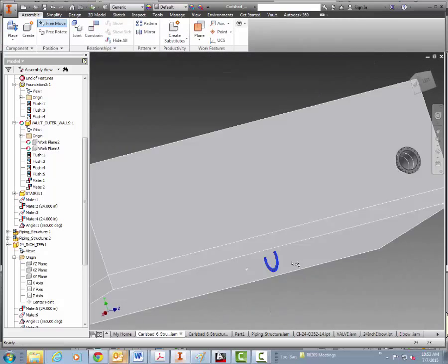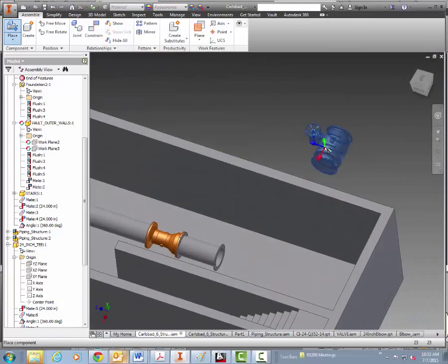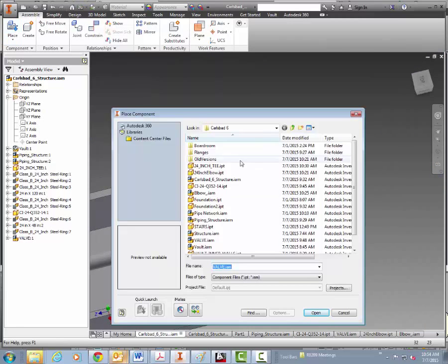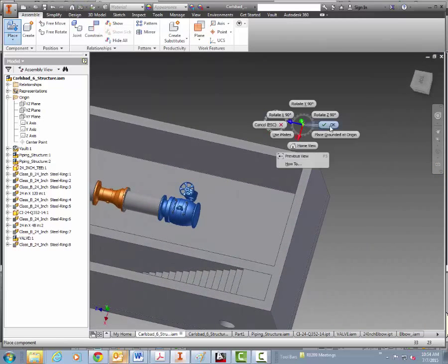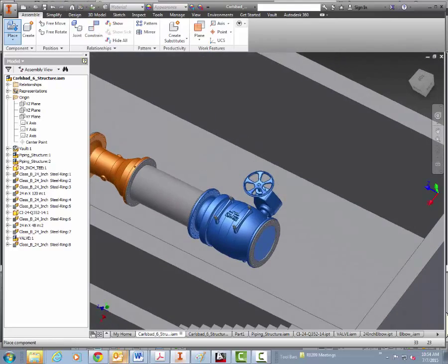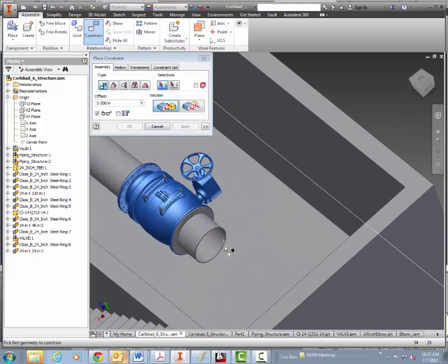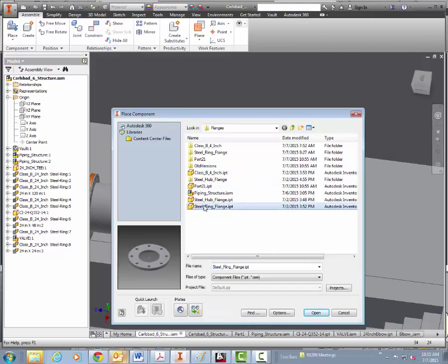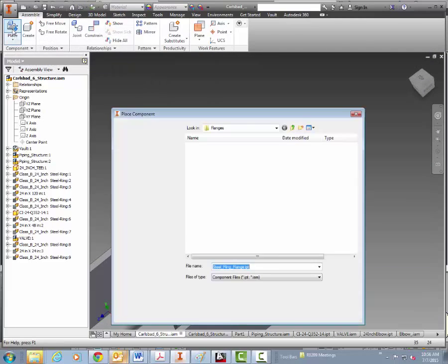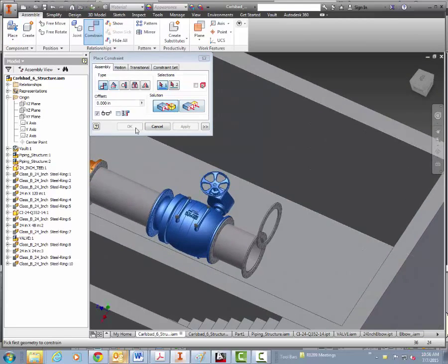The original drawing calls for the valve to be right next to the Venturi meter. We're just adding an extra piece of pipe here, and we're going to add the Venturi meter, or the valve, to the flange off that pipe. Now we're building it piece by piece. You can build the pipes with the flanges and then add them in later. The pipe is actually an I-part too, and has different sizes that are predetermined based on the table.